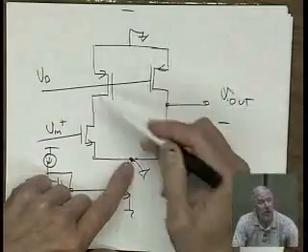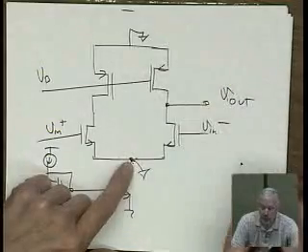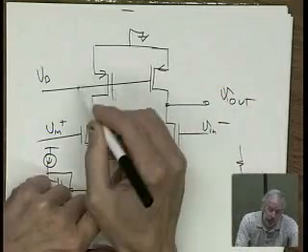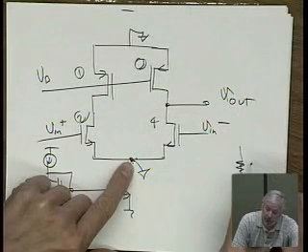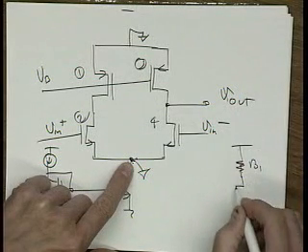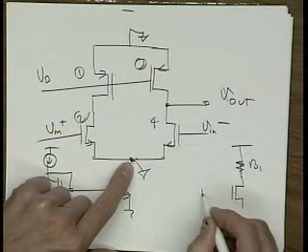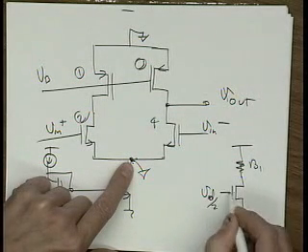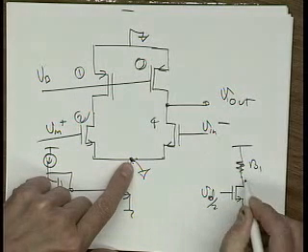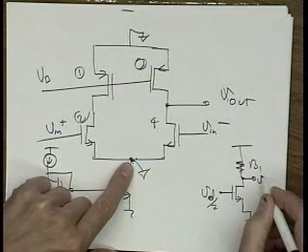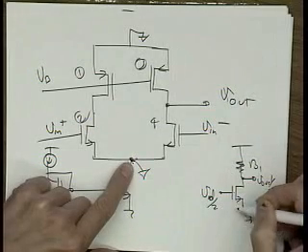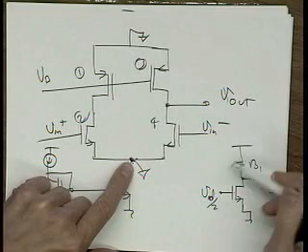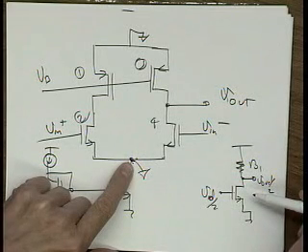We can do the old half circuit analysis just like we did before. Let's call these transistors 1, 2, 3, 4. So this is R01, the half circuit, with Vin differential over 2 going to a virtual ground, and Vout differential over 2. We can find the poles of this just like we did for our inverter case, and it will be pretty much the same situation as before.